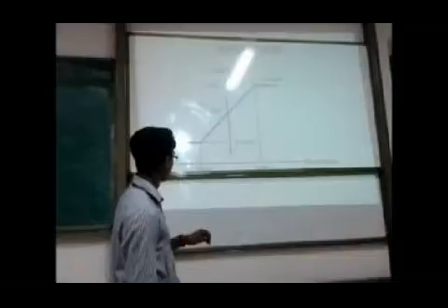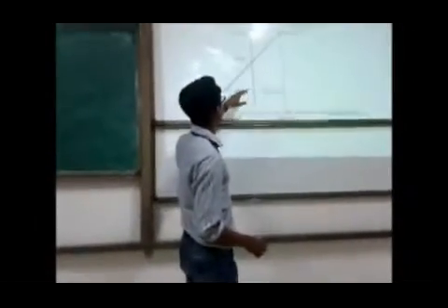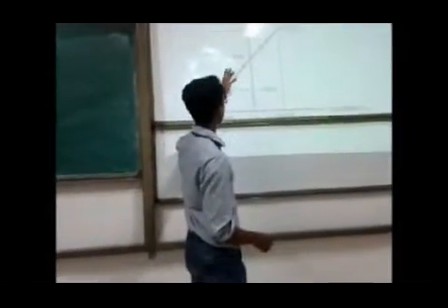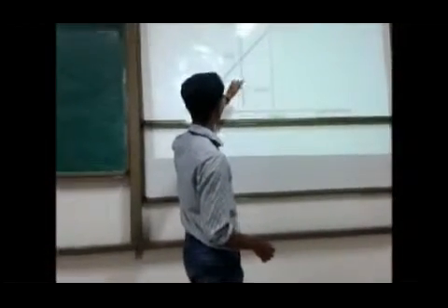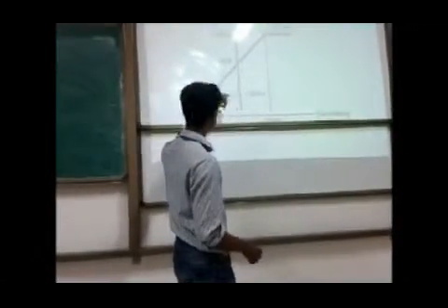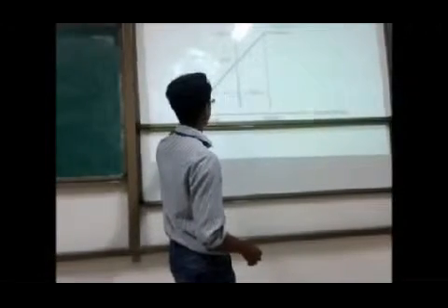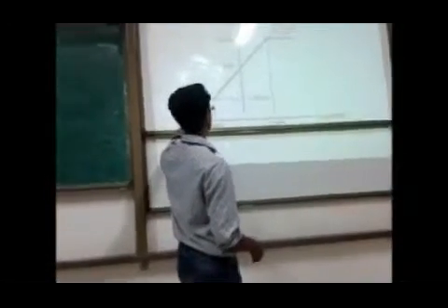This is the waveform of the current sensor, and when there is no current, we will get 50% of our VCC as output voltage. When the current is increased, it will reach around 75% of our VCC. When it is decreased, it will reach down to 25% of our VCC. After that, it goes to saturation.